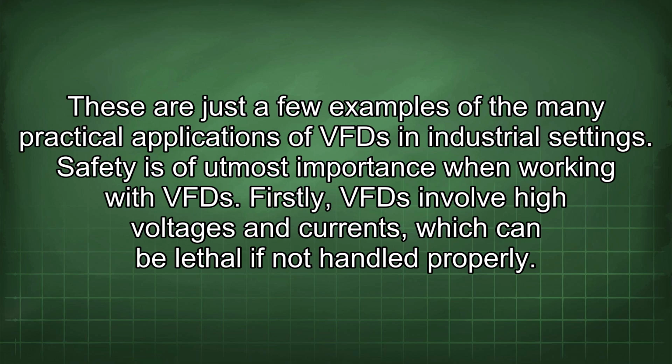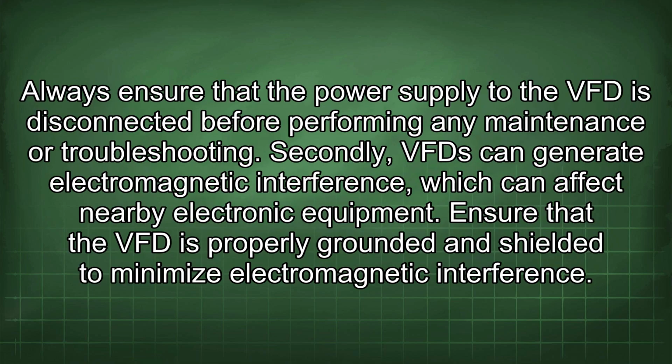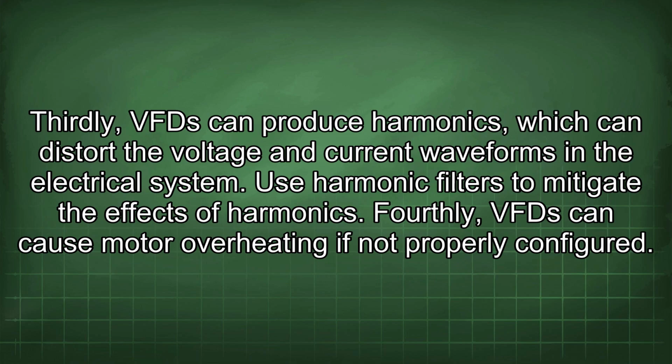Safety is of utmost importance when working with VFDs. Firstly, VFDs involve high voltages and currents, which can be lethal if not handled properly. Always ensure that the power supplied to the VFD is disconnected before performing any maintenance or troubleshooting. Secondly, VFDs can generate electromagnetic interference, which can affect nearby electronic equipment. Ensure that the VFD is properly grounded and shielded to minimize electromagnetic interference. Thirdly, VFDs can produce harmonics, which can distort the voltage and current waveforms in the electrical system. Use harmonic filters to mitigate the effects of harmonics.